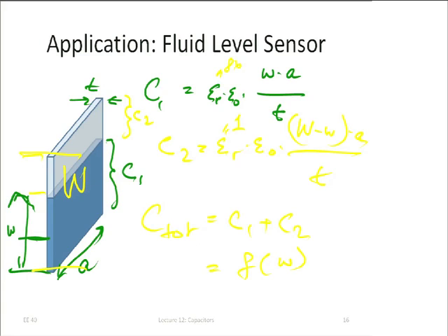So what it has inside is simply two of these basins, and the water goes from one to the other depending on how you tilt it, and then you measure the two capacitors, you compare them, and calculate the angle, and that's what you display. It's exactly the way this is done. And of course, we will need some kind of a circuit that allows us to measure the value of capacitance, and we're going to build this next time, but let me just show you a few other applications.